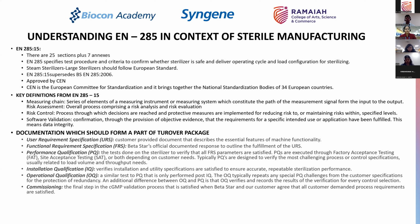These are generally around any finishes. So if you had specified that you want a mirror finish with a 0.38 Ra value for the internal chamber, and when you measured it, it came to 0.6, you cannot go and polish the chamber at your factory. It has to be done at the manufacturer's factory itself. So factory acceptance test is an important aspect.